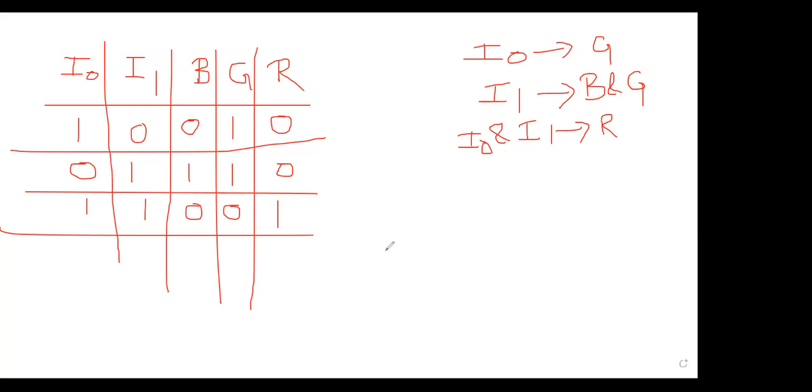Other people, make it fast. Already we are running out of time. Make it fast. Ashita, madam, how many outputs do we have? Only 3 outputs, so we have to take 3 coils. If you start making the program from NO/NC, your program will be wrong. Better you start from the output.